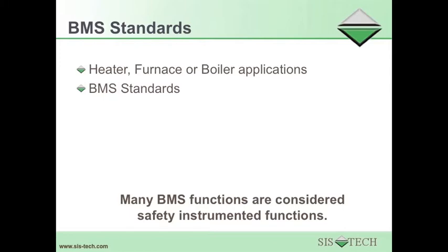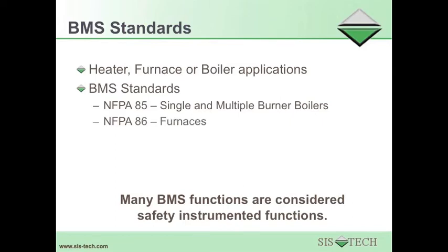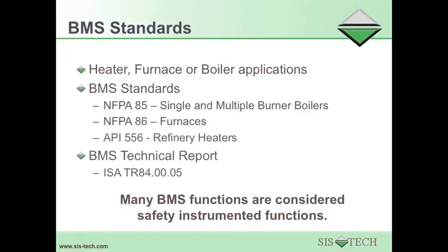Our design fulfills the requirements of the following standards: NFPA 85 for single and multiple burner boilers, NFPA 86 for furnaces, and API 556 for heaters. The ISA Technical Report TR84.00.05 for identification of safety instrumented functions in BMSs.